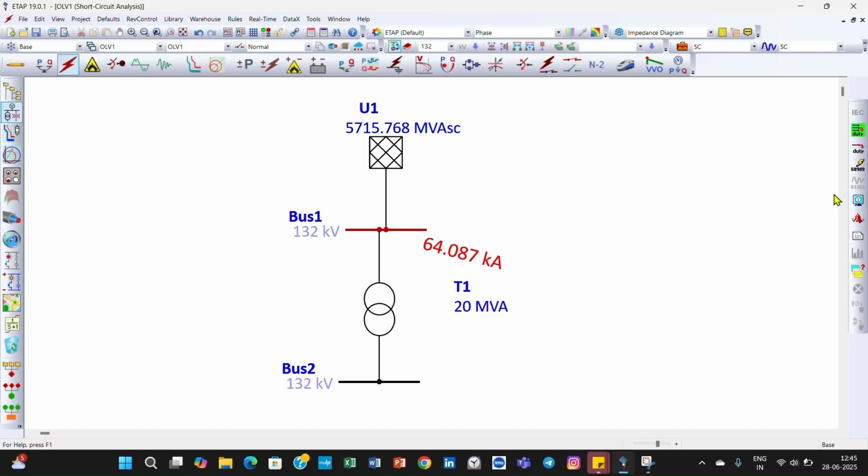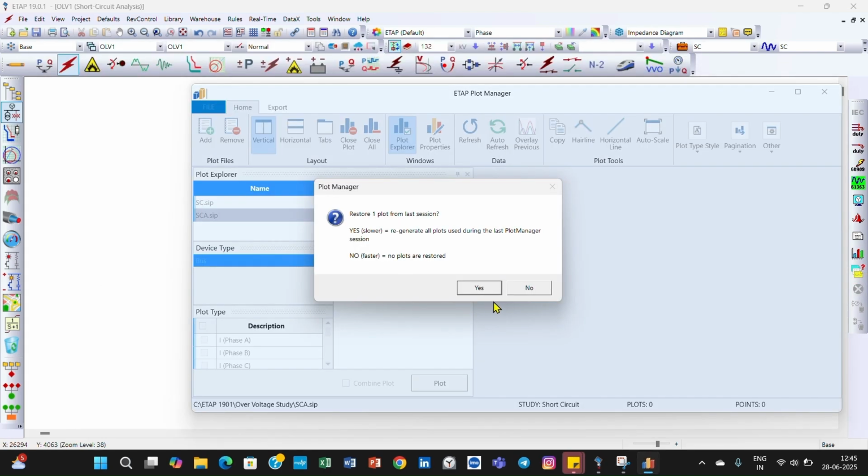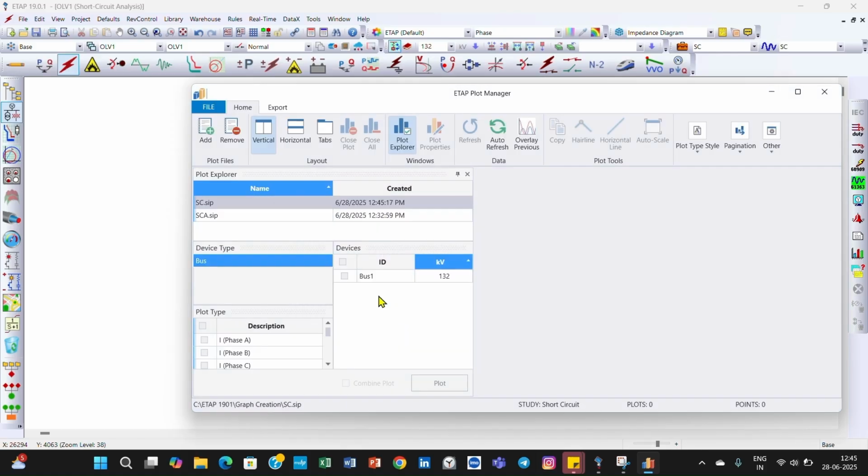This is the transient short circuit analysis run, and then click the graph. This window is the short circuit plots. Okay, now actually I have plot. Click no. Bus 1 is faulted. Okay, we will select one phase. There are three phases, we will select one phase, I phase. We will see the total short circuit current I. We will also see the symmetrical short circuit current, that is IAC, the symmetrical value, that is 25 kiloamperes, and we will also see the DC component.